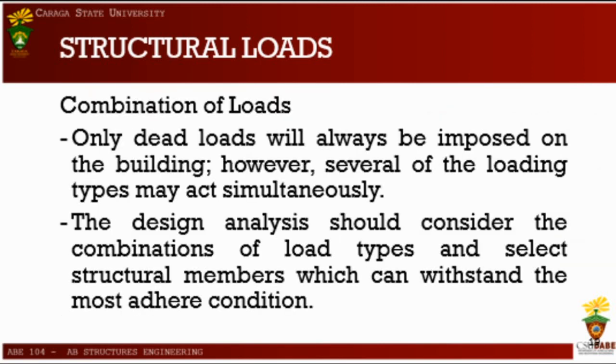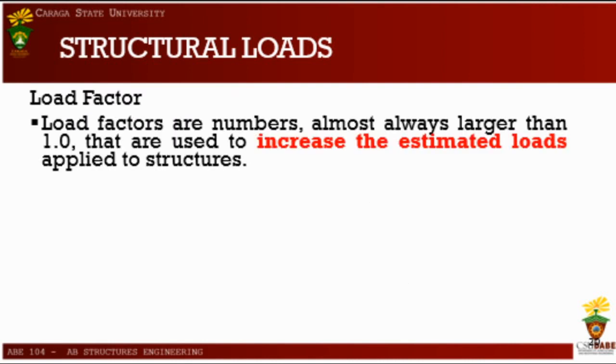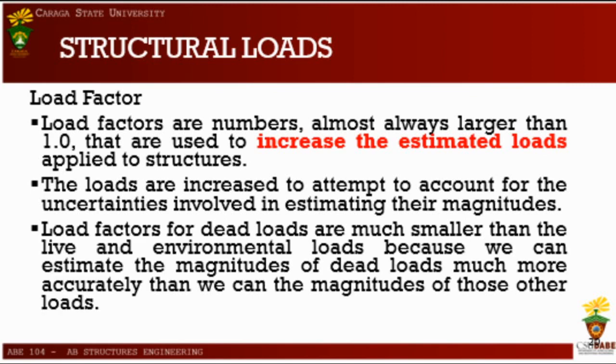You also have this combination of loads. Only dead loads will always be imposed on the building. However, several of the loading types may act simultaneously. The design analysis should consider the combination of load types and select structural members which can withstand the most adverse condition.